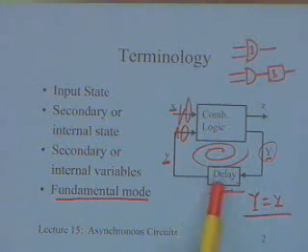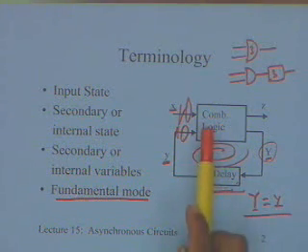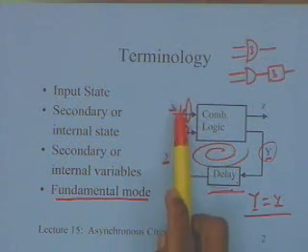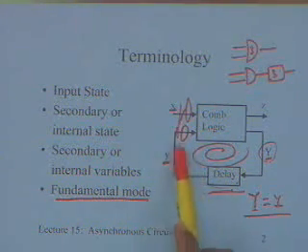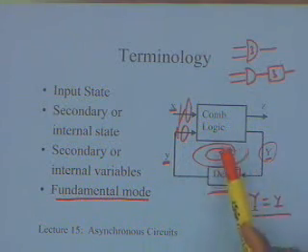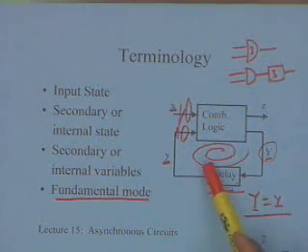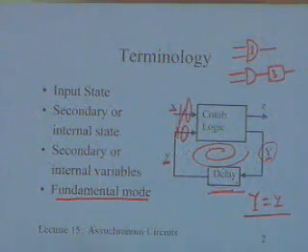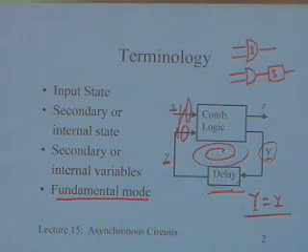What we say is all the delay is concentrated over here. This is an ideal block, and whenever an input changes, it will set off some transients here, and these transients will die down in due course of time, and we will reach a next stable state. And no input change is permitted till then, and once again the input changes, I will repeat this process.